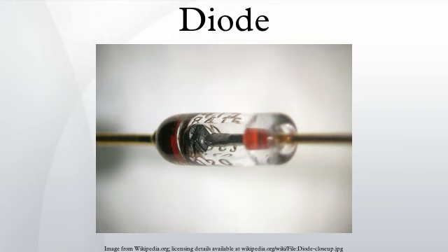Normal diodes, which operate as described above, are usually made of doped silicon or, more rarely, germanium. Before the development of silicon power rectifier diodes, cuprous oxide and later selenium was used. Its low efficiency gave it a much higher forward voltage drop, and required a large heat sink, much larger than a silicon diode of the same current ratings would require. The vast majority of all diodes are the p-n diodes found in CMOS integrated circuits, which include 2 diodes per pin and many other internal diodes.